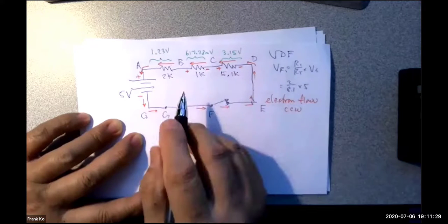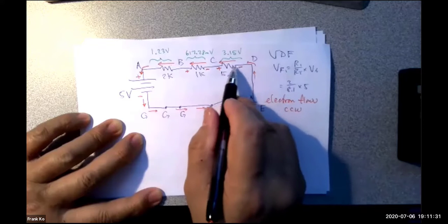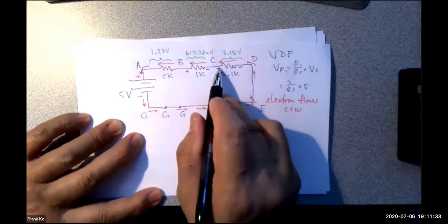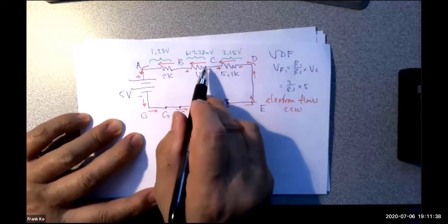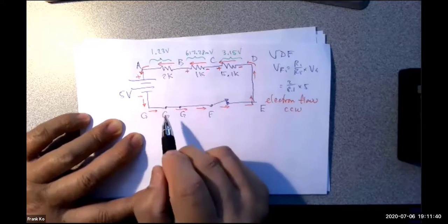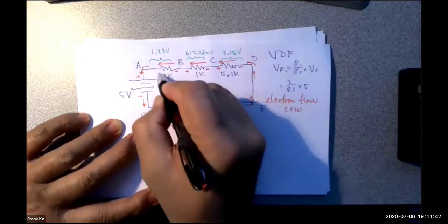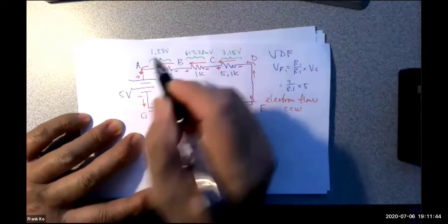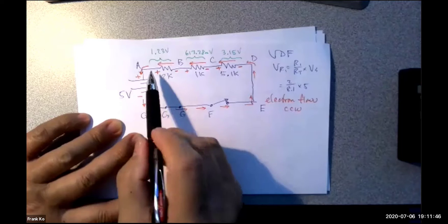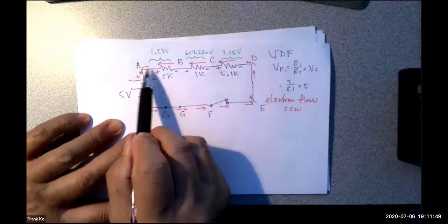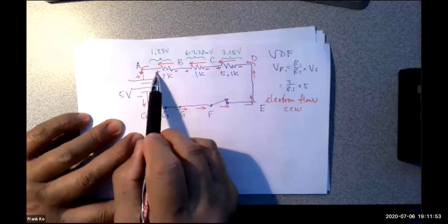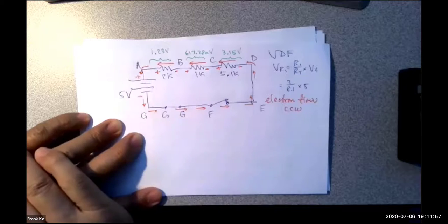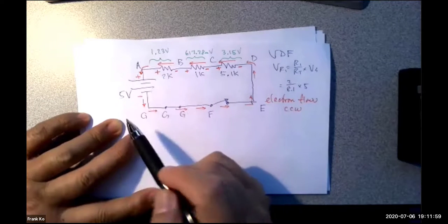That way it's consistent. It must flow through any device from the negative side to the positive. So as the current flows through the device from the right to the left, the right side must be negative, the left side must be positive. And the same must be true for this, yes? And do we have, in fact, a resistor that is physically attached to the positive side of the source? Therefore, the lead of that resistor shares the same polarity as that plate of the source. So this is positive, that will be positive.